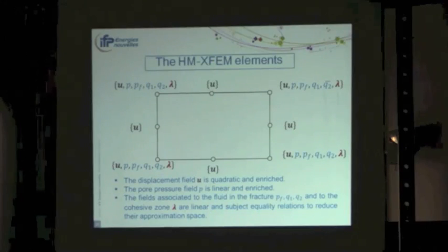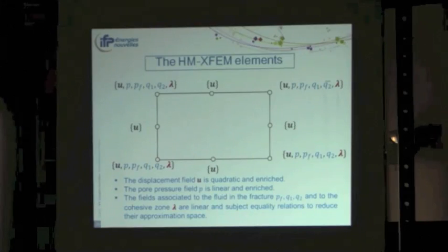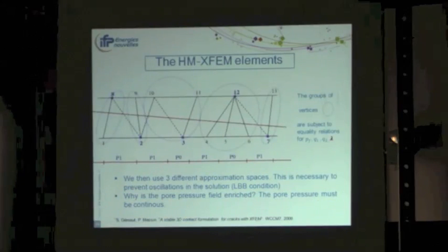So the pore pressure is linear and enriched. It's also an XFEM field. And the fields that are associated to the fracture, so the pressure in the fracture, the fluxes and the Lagrange multipliers, are linear, but they are also subject to equality relations to reduce their approximation space. So they are not necessarily P1, they are what we call P1, P0.